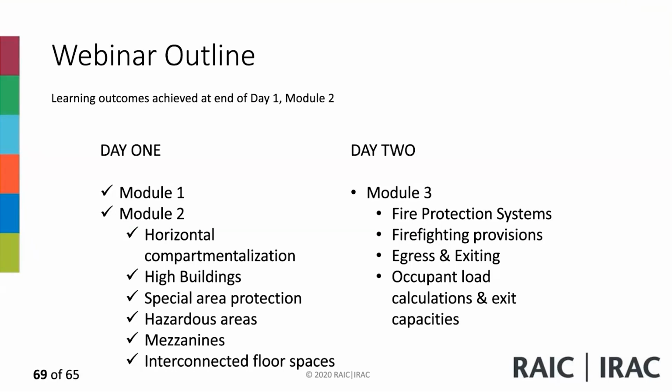Okay, in 3211, we looked at the type of mezzanines, and the aggregate area of mezzanines that are not superimposed. This is only for consideration of whether they are considered a story or part of the floor area. If they are not a story, then they're not considered floor assemblies. They will not be protected similar to other floor areas for stories. So you've got to take a look at that first.